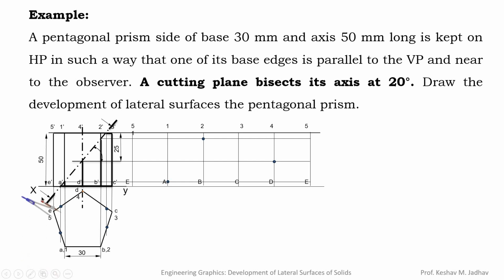So to locate these points, make use of this compass. So measure distance of this point. So this is D line, and on this D line take distance in compass from E towards D. So this distance we have to take from E towards D on baseline on bottom surface. So from E towards D we can measure the distance and we can locate the point.